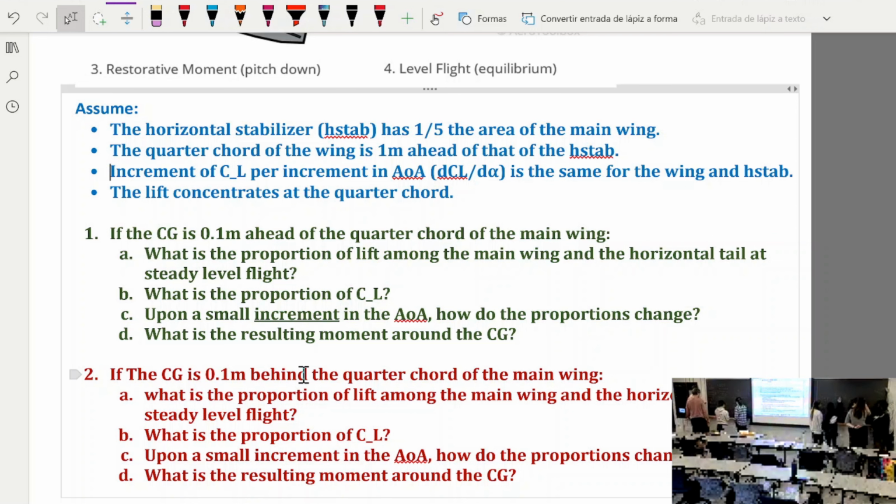So then this should be negative. Yeah. Okay. Good. The lift gets more and more here. Another thing is that this is providing downforce, right? So if you increase the angle of attack for both, the positive force is going to get more positive. How about the downforce? More negative, yeah. Less negative? Same thing here.